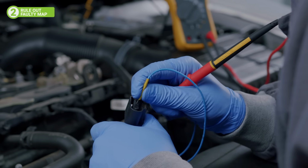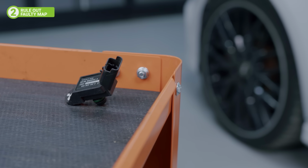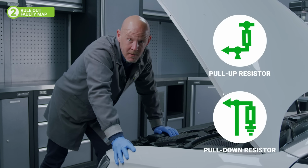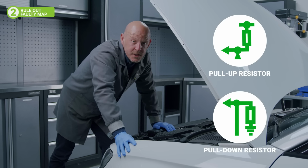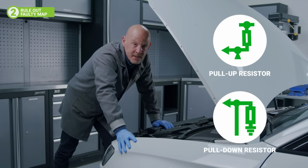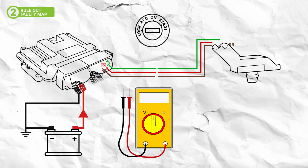In this video, we're testing a MAP sensor where the signal wire is monitored by a pull-up resistor. Knowing which type of circuit your sensor is monitored by is crucial to the diagnostic process, as you'll find good voltage readings are different if your sensor utilises a pull-down resistor. Like any circuit, we need to verify that the MAP sensor is receiving a good ground and power supply from the ECU. To test this, ensure the ignition is off and disconnect the sensor.